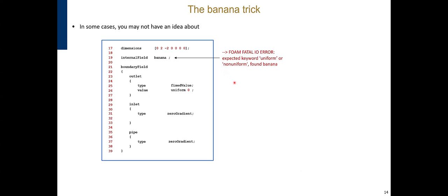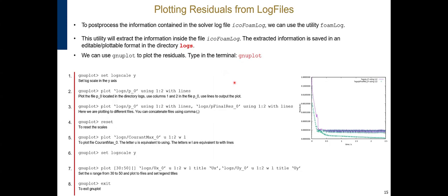Okay, now one more thing that I would like to talk about, although we would be implementing it, is the post-processing. Once you obtain your solution, you need to at least monitor your residuals. You want to see whether or not your case is converging.